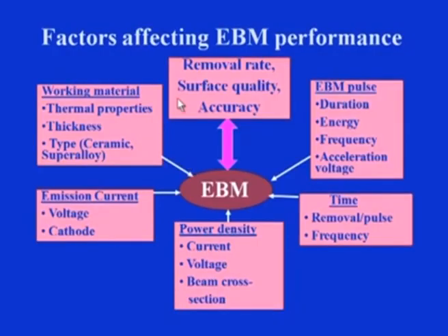Therefore, the thermal properties of the material, how fast the material can acquire heat or get heated, will affect the material removal rate or the performance of the process. Similarly, as the type of material changes, like ceramics, they have different thermal properties, and superalloys, they have again different thermal properties.